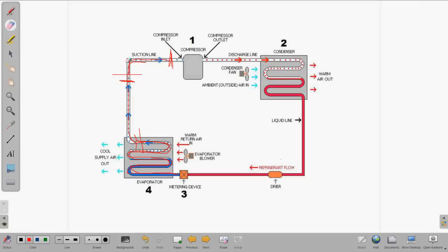Okay, so liquid comes back to the compressor. It is now mostly vapor, but there is still liquid. The compressor can't compress liquid, so it starts to run that compressor pretty hard and starts to damage the valve plates and everything that's going on in that compressor with the liquid. And if it's doing its job, it will compress that refrigerant down, and we're going to have hot gas going into the condensing unit.